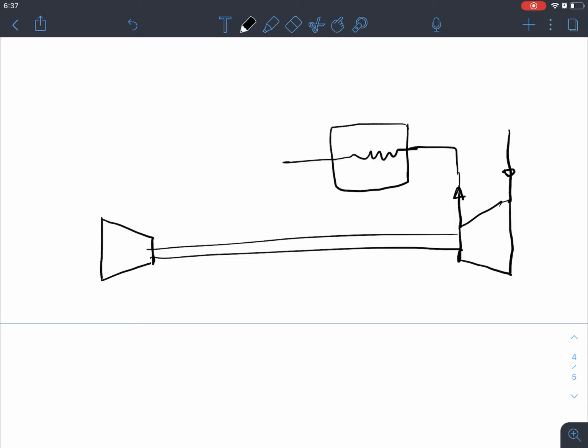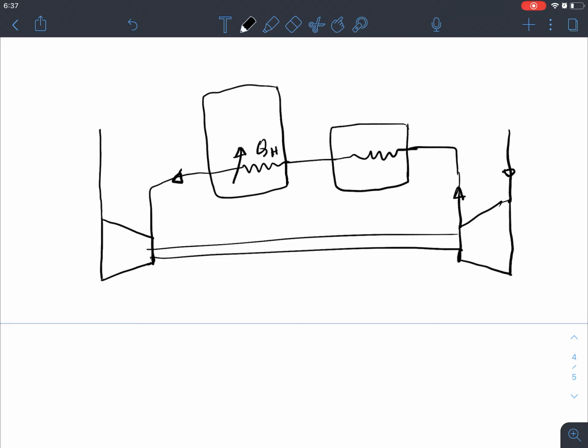From that heat exchanger we can take that exhaust or output to a regeneration unit. In this regeneration unit, it will reject some heat, QH, and then it will become low temperature, still high pressure. Then that high pressure gas will be expanded through this turbine, and the outlet of this turbine goes through the regenerator unit, where it is absorbing the heat now.